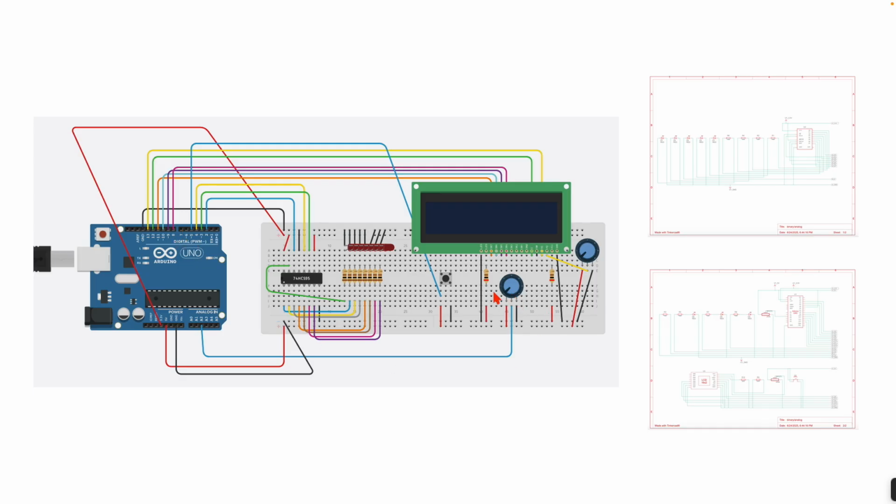And then the potentiometer is similar to that, except with a bigger range of numbers than 0 or 1. It's variable, it's on a spectrum. It takes in power and goes to the ground, making a circuit through the potentiometer. When you turn this, it applies more or less resistance onto the current, and then it returns the value of that resistance in this cable into an analog input.